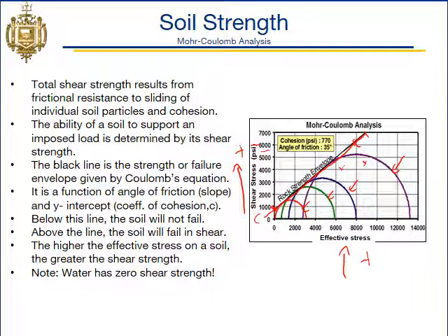So more effective stress essentially means more strength. A good mental exercise for this is, take your hand and place it gently on your desk, and then move it left and right, and it moves fairly easily if you don't push down very hard. If you do that test again, but then push down as hard as you possibly can and try to move your hand left or right, it doesn't slide very easily. So that same phenomenon happens in soils. The more stress that's being applied to the particles, the more friction between the particles, so the stronger essentially the soil becomes.